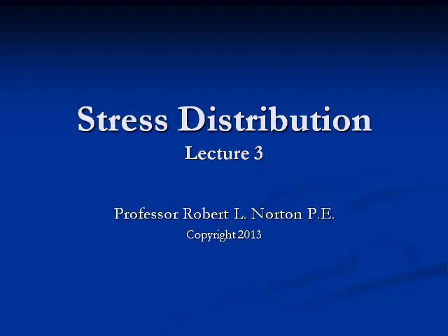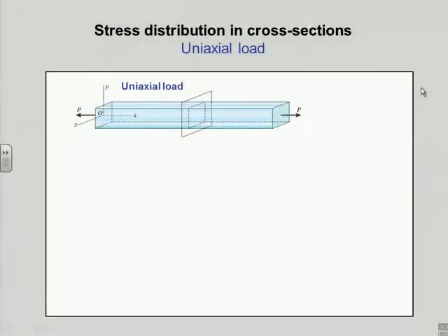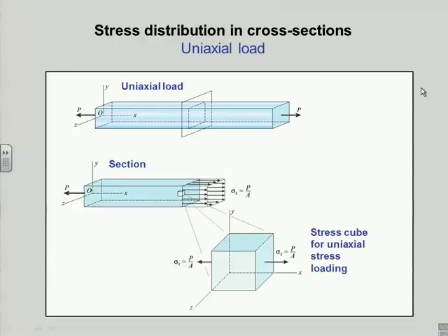We're still on the topic of stress with a little more detail today, not generic stress, but let's see how stresses show up in various parts with various loadings. I showed you the simplest possible one yesterday. It's here again. I have a bar in tension. Could also be in compression if I turned the loads around. And I'd have the same formula, P over A, for the stress. And as I said yesterday or the day before, whenever it was, this is the simplest arrangement, and it's one of the few that has uniform stress distribution across the cross-section.